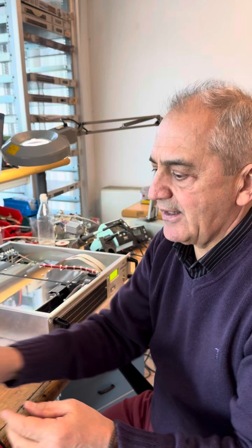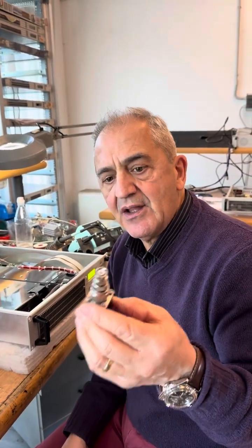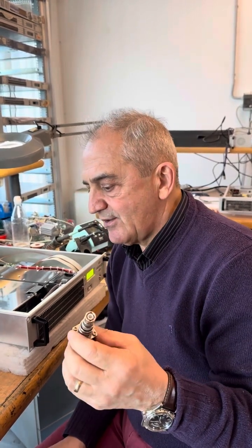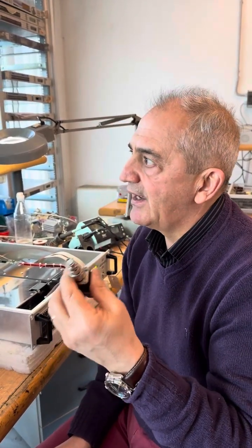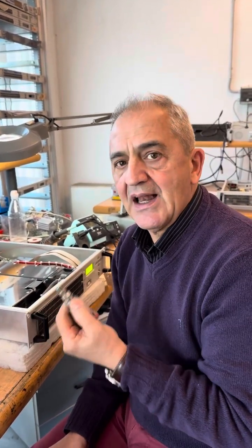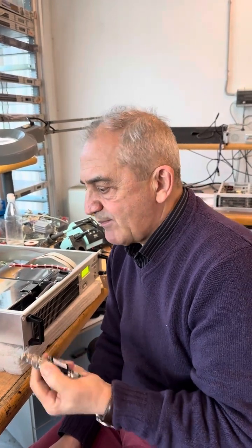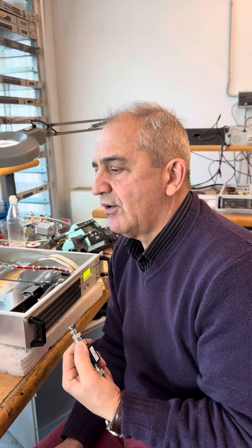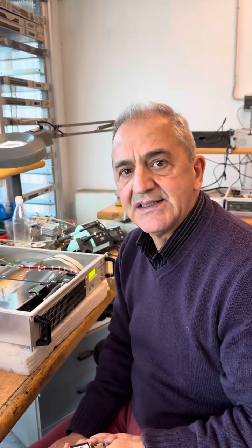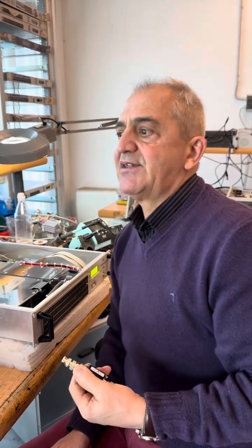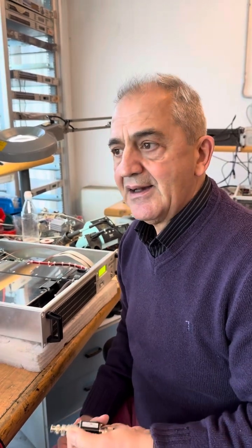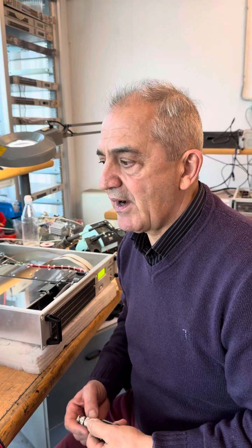I will show you what happens in the measurement when I introduce a 10 dB attenuator. This is just to show how the harmonics and the intermodulation distortion of the spectrum analyzer work. You must always pay attention, because sometimes, for example, if there is a power meter in the system, typically there are diodes to get the forward power measurement.